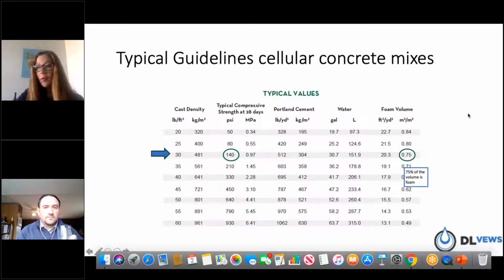Right. I'm going to ask the question that came into chat. Is there a max distance cellular grout can be pumped if a project is a 2,000 foot tunnel, for instance? That's a wonderful question. To date, in my experience, and depending on who you talk to, everyone's experiences are going to be slightly different. I can tell you from some case histories and some bulletins that we've had success on projects pumping several thousand feet, 10,000 feet plus. So you're talking miles.